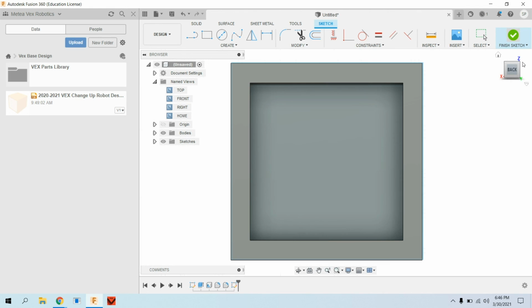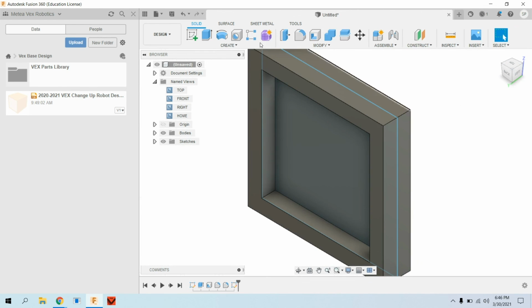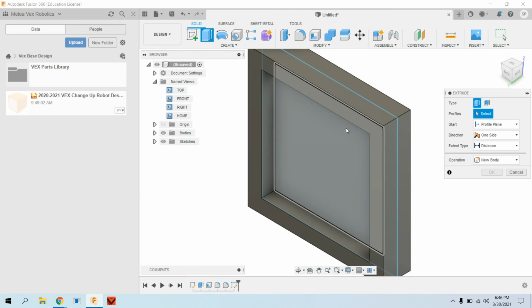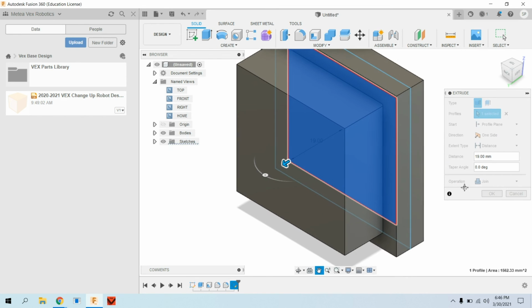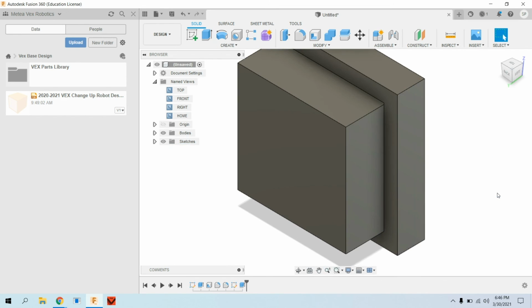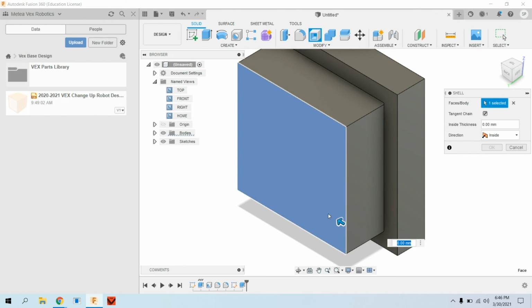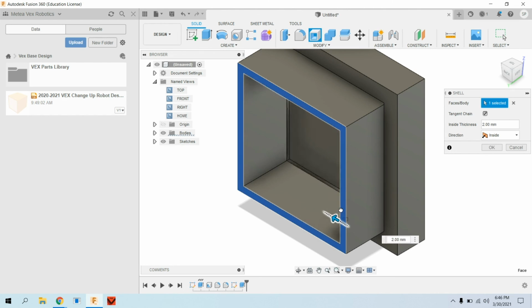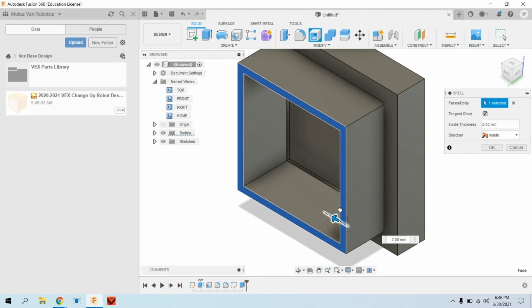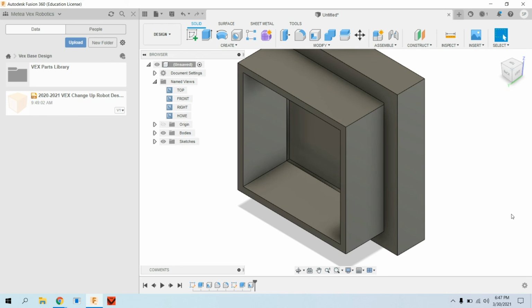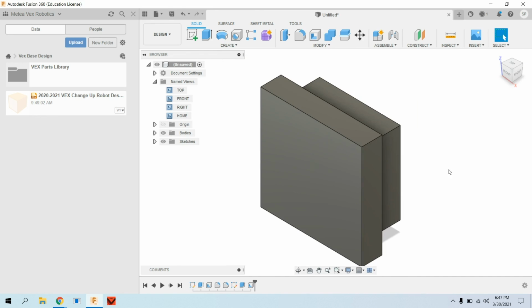Create the sketch. Move it to the back view. I'm gonna extrude that. And you're gonna select your face right there. And there you have your new box. You can shell that if you like. And you can do different shells. You can see as I'm moving this, you can make it smaller, bigger, like that, and it looks like that. So basically right now you have a 2-part box like that.